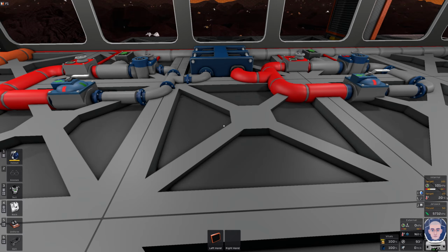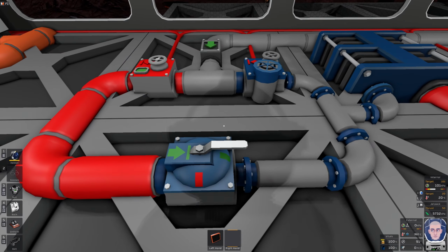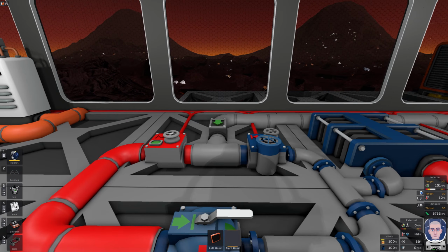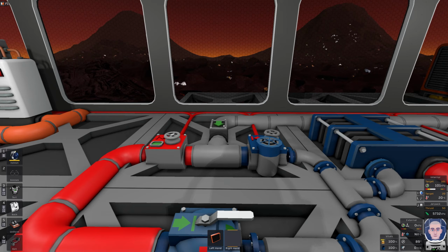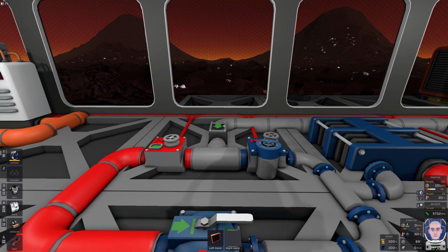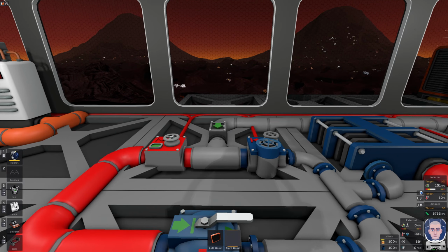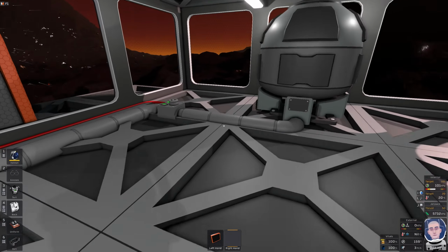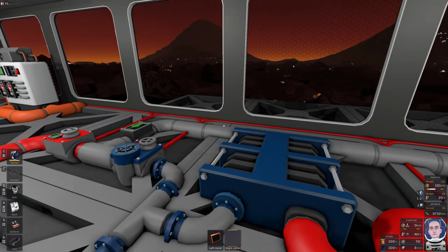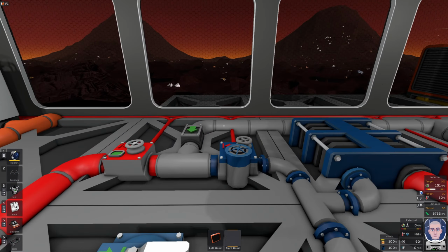Okay, so we're going to try this again, but with 2 stages here. So here we go, our first stage. You notice we do not have the hot side connected to outside yet, or to a sink. The other change is that we have a one-way valve for the refrigerant. This is so we only need one pressure regulator for multiple stages, or all the stages. The regulator is down here, so we pressurize the line, and then each stage uses just a simple one-way valve.